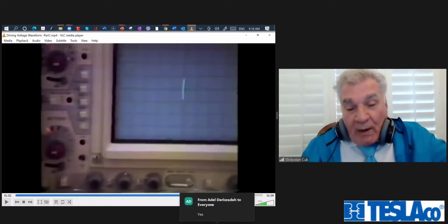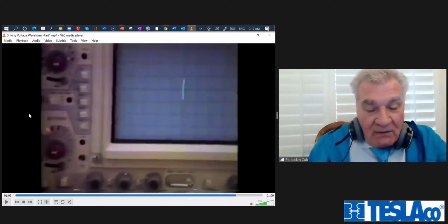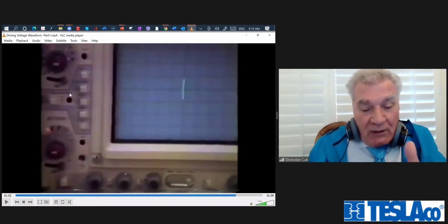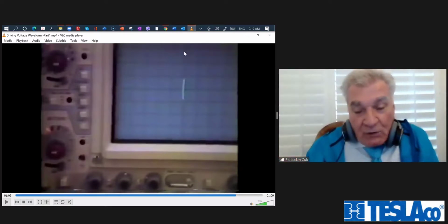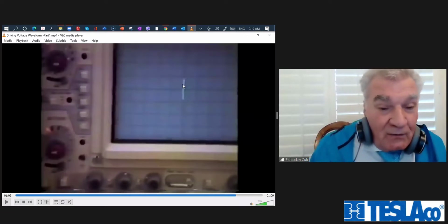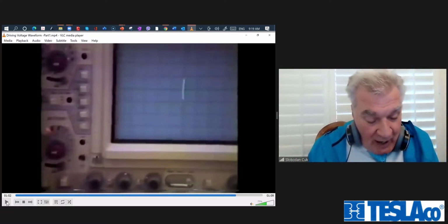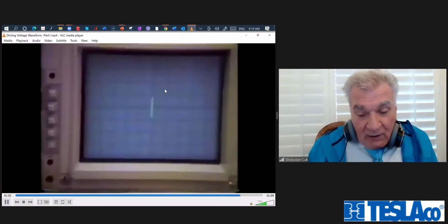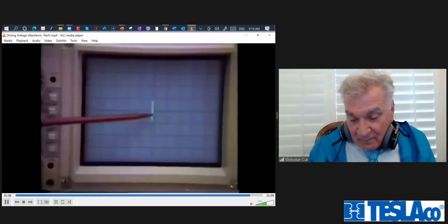On one scope, I'm looking at the voltage drive, and the resulting current and resulting flux in the core. Now, when I put the flux as a function of current, I'm using the other scope in the so-called XY coordinates, and of course, what will that show? It will show the real BH characteristic of the magnetic material, and you see that high slope.